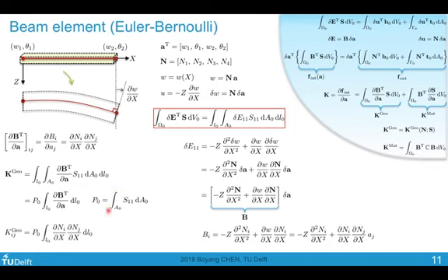When we perform the integral of S11, we obtain our axial force P0. So we can bring this P0 outside of the integral over L. This is, of course, assuming that the axial applied force is constant through the length of this beam. Then we arrive at this expression.